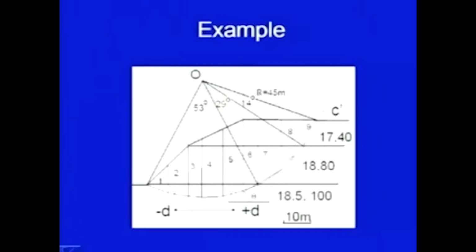These slices are trying to destabilize; if I take the vertical weight and then its component parallel to the sliding surface, the components will be in this direction, here it will be in this direction, and so on up to here, where it will be almost horizontal. Now, when you go towards this side, the component tangential to the failure surface is in this direction. So, they are trying to do the opposite. So, we have taken D as positive in this case and D as negative in this case.